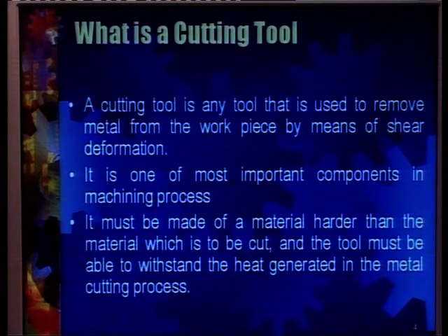And the second thing is that in the cutting process, when the cutting is going on, a lot of heat is generated, and in case the material of the cutting tool is such that it gets softened at elevated temperature, then the actual purpose of the cutting will be lost, and the material will be much softer than that of the workpiece, and the same problem will occur, and we will be required to sharpen the cutting tool again and again, which will not be economical, as I have already told.